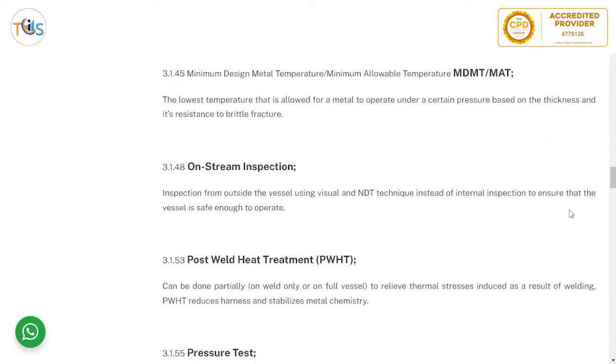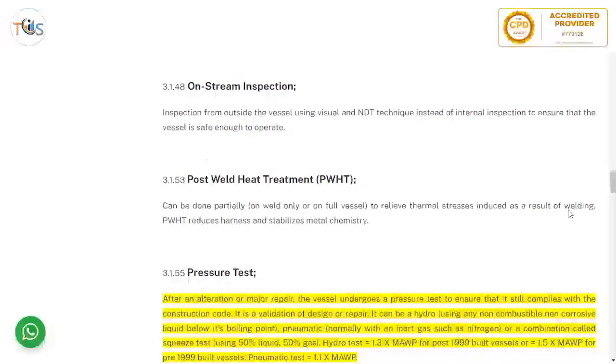Normally they add 8 degrees centigrade to that, and that would be the minimum design temperature in case of environment. In case of process, it would be the minimum temperature of the process fluid during operation.